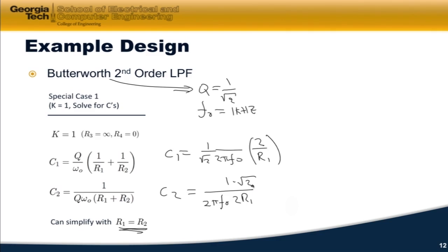So trying out different Rs, I reached the conclusion that by letting R1 equal 1 k ohm, a resistor value that's found in every resistor bin in existence, I get C1 is equal to approximately 0.11 microfarads, and C2 is approximately equal to 0.22 or so microfarads.